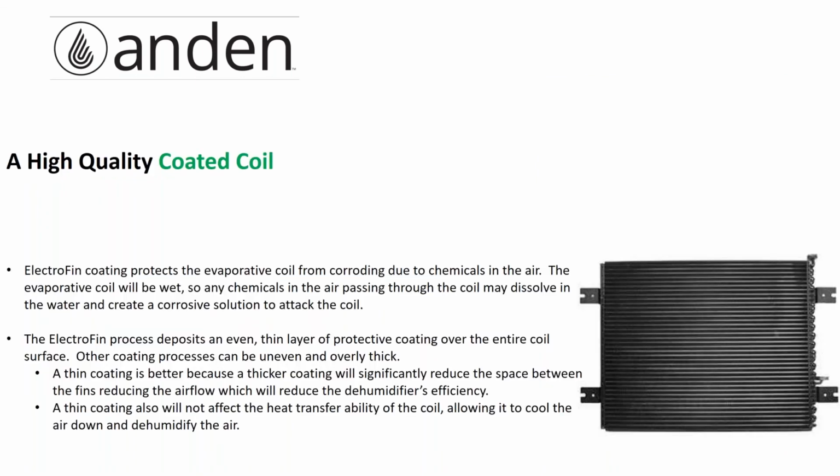And then finally, a coated coil has to be there. Every nutrient you put in the soil, every fertilizer that you throw inside the ground is designed to eat away at a coil of an air conditioning system and a coil of a dehumidifier. And if you're bringing air across that coil and your coil is not protected against chemicals, that coil is going to fail.